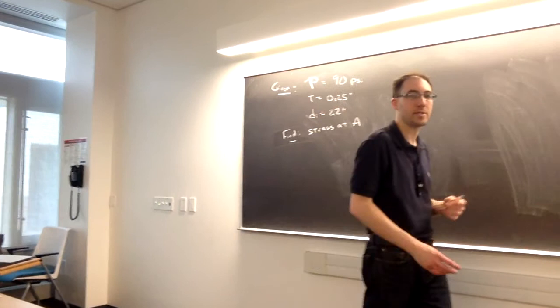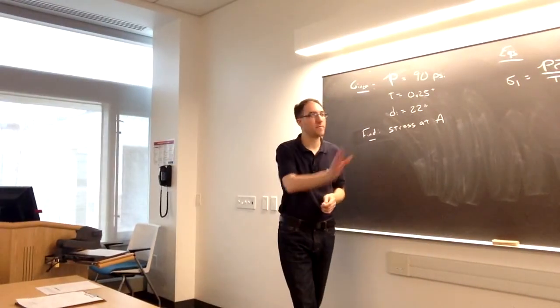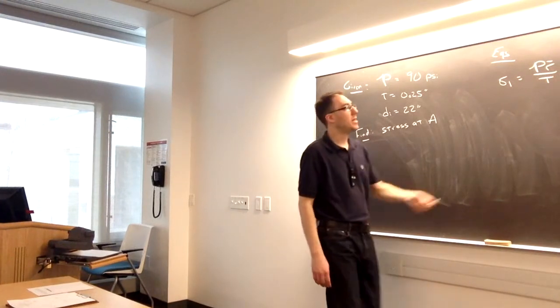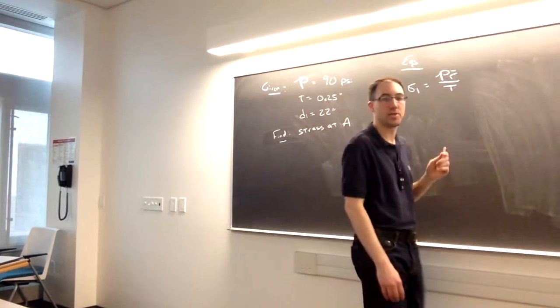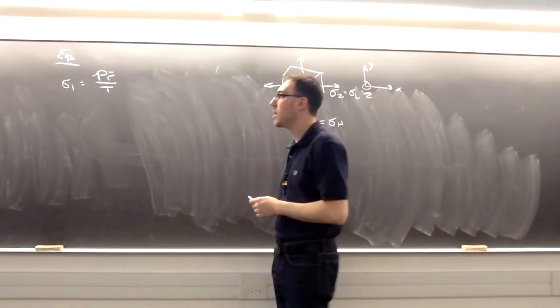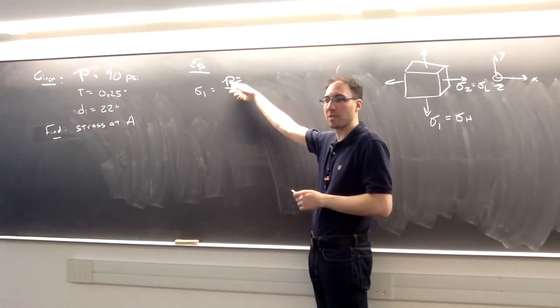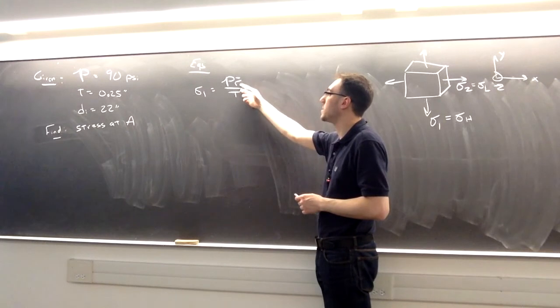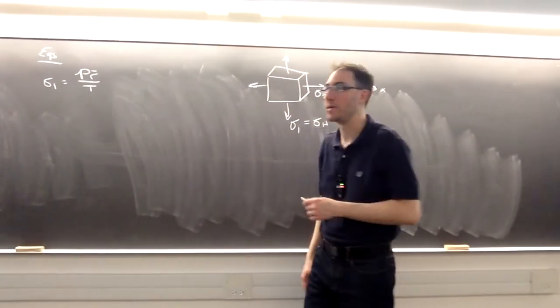So this is where we can use the equations that we just developed. We know that along the radial direction, from the hot dog example, the stress along the hoop is going to be PR over T. And then the stress along the longitude will be PR over 2T. But again, by the way I'm formulating it here, this is going to be the internal gauge pressure, the wall thickness, and then the mean radius of the pressure vessel is what we're going to use.